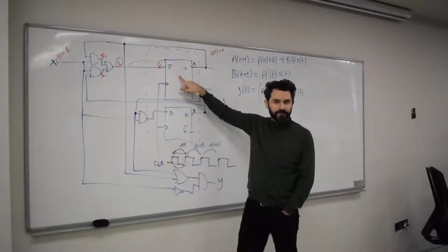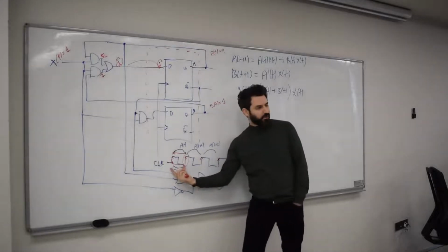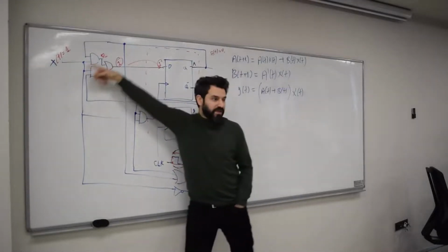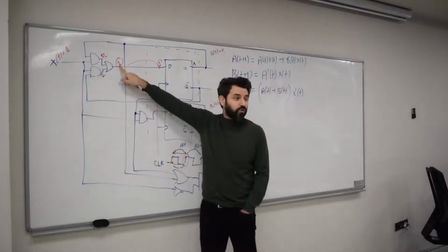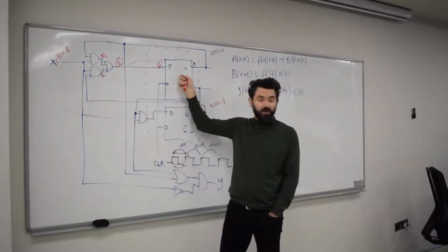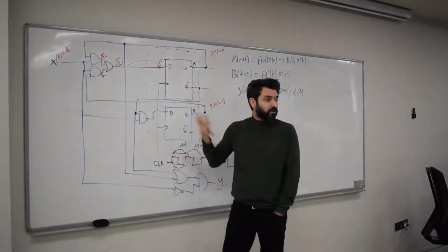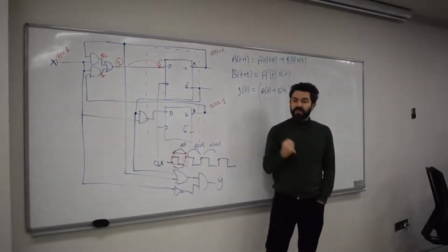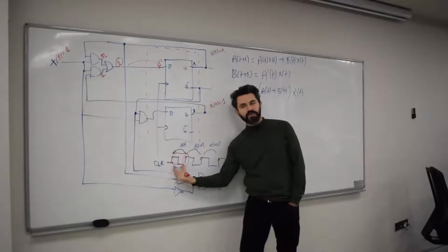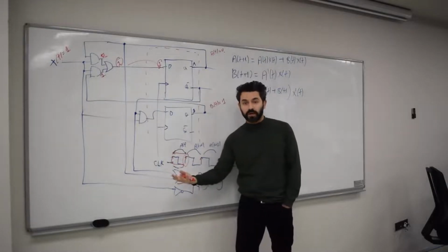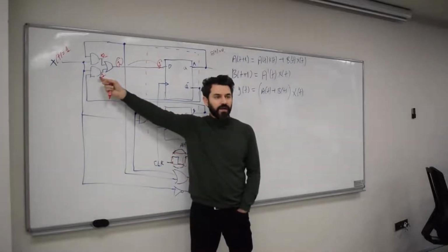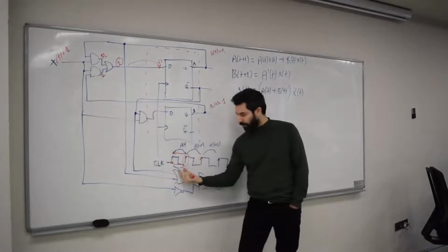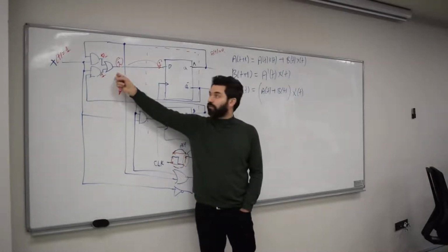In other words, you get this one inside of the circuit, so that's going to be stored now. Some people ask me, how is this period determined? Well, that period is usually determined based on your combinational circuit delay. If this small delay that I've drawn here is bigger than the period, then the value 1 couldn't be determined before you take this value inside the flip-flop. That would create a confusion, and your circuit would not work properly. So people make these periods smaller and smaller, because a smaller period means a faster circuit, until they become so close to this gate delay that they could not shrink the period more.